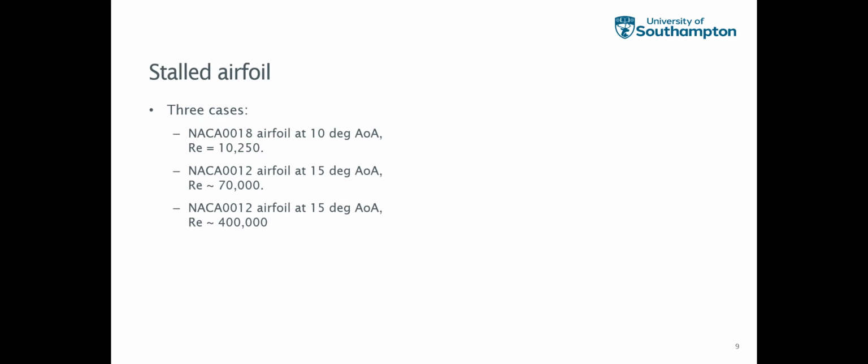And we've done a lot of work in case of the flexible and rigid wings at these Reynolds numbers. So we wanted to test how the variational method also applied for data assimilation for this high Reynolds number case. And in all cases, we are performing, of course, a steady state assimilation. We're using mean fields as our input data from experiments, typically from particle image velocimetry. And we are performing the momentum source correction, the correction term that's in the momentum equations.